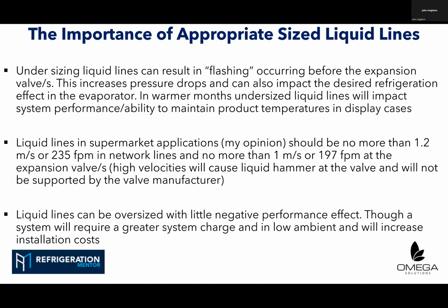Real quick, it was interesting that you said, Trevor, that you saw a lot of 5/8" lines for the liquid line. In the US, depending on what kind of defrost they would use, if you've got hot gas defrost, you would typically have a larger liquid line than you would actually need. So when you do reverse return and it goes through the evaporator, you want the liquid line big enough to get the gas back up the line so you don't increase the pressure.